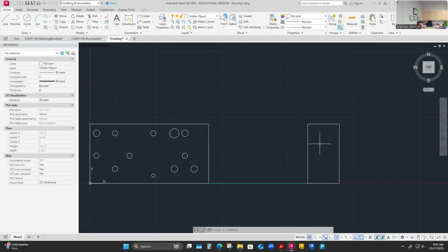If I projected all these across, it would make a really busy hidden line mess that would not add clarity. So we just drop the hidden line views there. We don't even want them. I mean, there could be an argument that some of these might need a section view, but I think we're just going to leave that unsectioned and just leave this as a straight up right side view with no hidden lines.